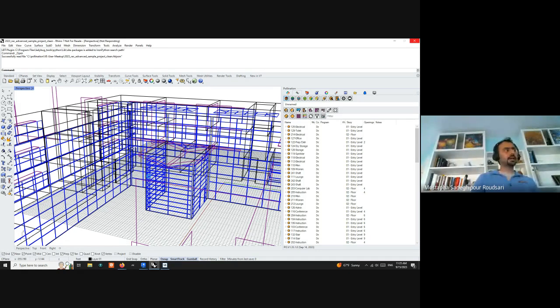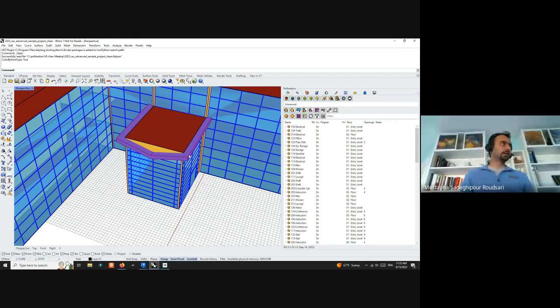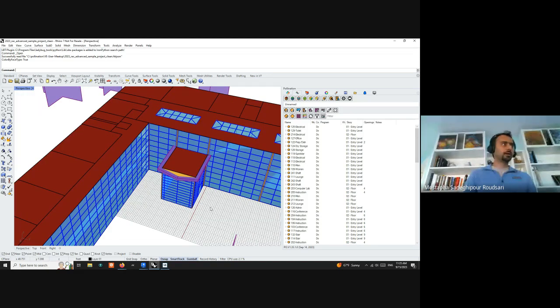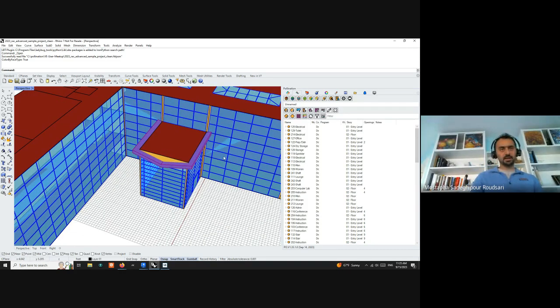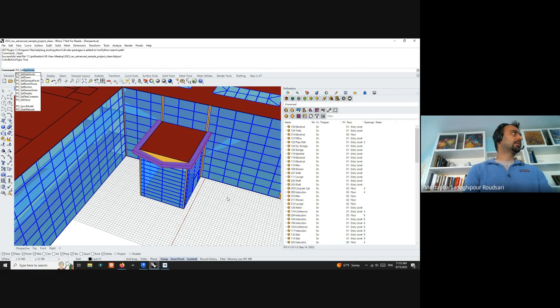to see this better. And actually, this is a good example of how to simplify shades. We have all these faces here, and you probably don't want all of those. Just one face is enough. So what I'm going to do is use the command PO select. The first thing is I'm going to try to hide everything else, to clean up so you can only see the shades.